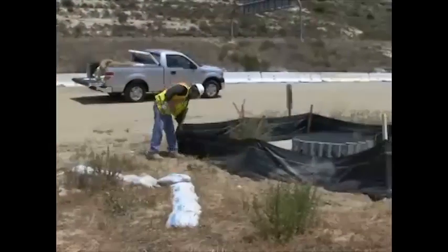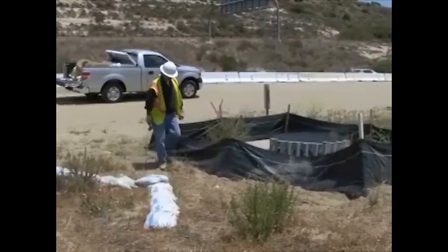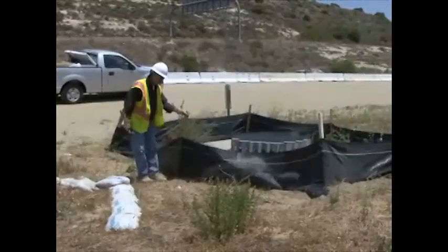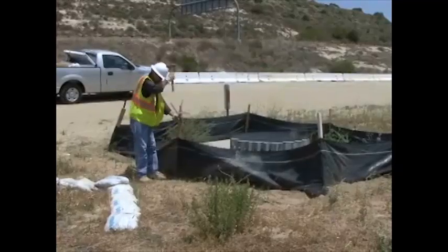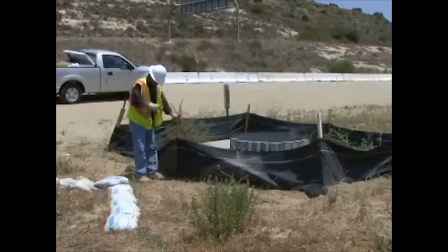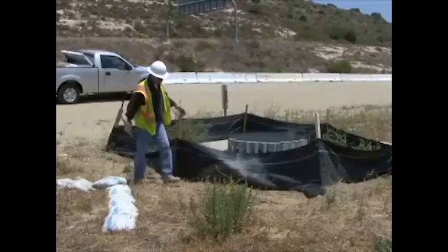Repair or replace the temporary silt fence when the silt fence fabric becomes split, torn, or unraveled. Repair a sagging or slumping silt fence with additional stakes or replace it. Replace broken or split stakes.